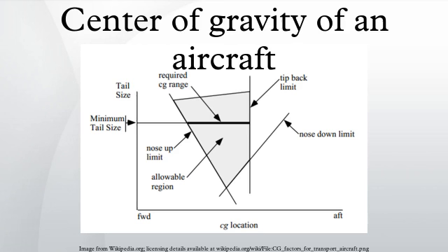The center of gravity of an aircraft is the point over which the aircraft would balance. Its position is calculated after supporting the aircraft on at least 2 sets of weighing scales or load cells and noting the weight shown on each set of scales or load cells. The center of gravity affects the stability of the aircraft.